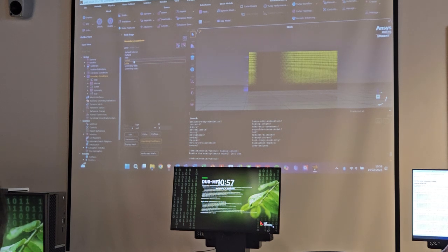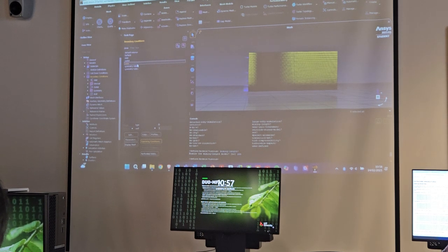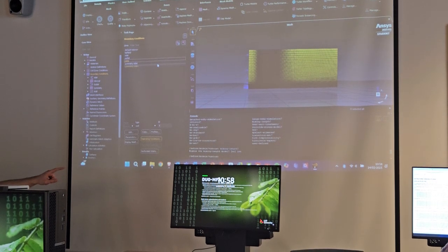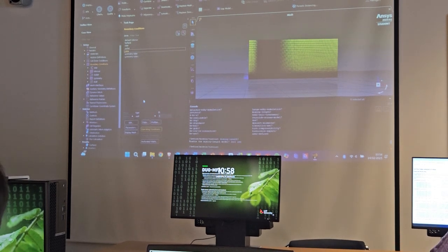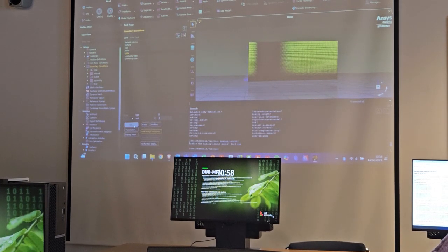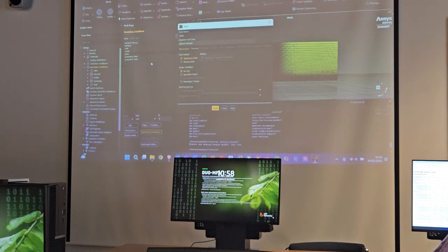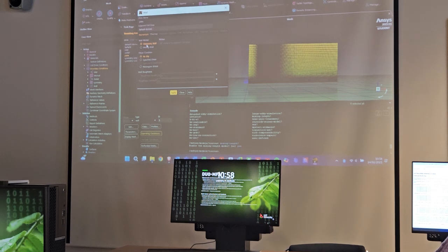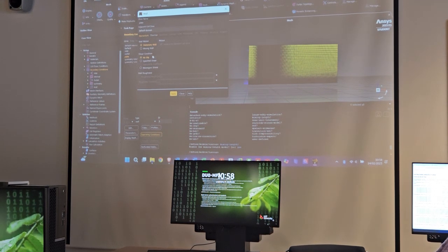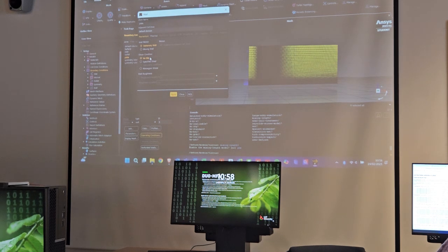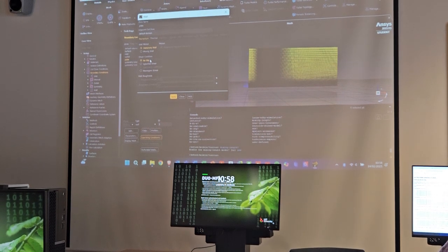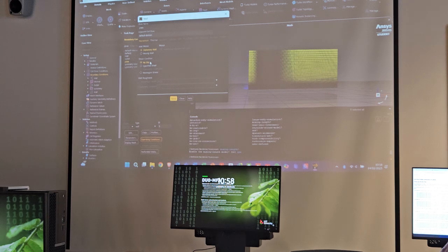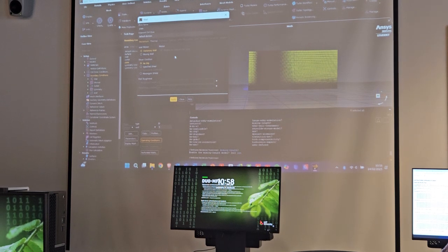Then we move to plate. The plate is the solid adiabatic wall. Edit. Here in the momentum tab we can set that this is a stationary wall, so it's not moving. Then the shear condition. We said this is a no-slip wall, since the relative velocity between the fluid and the wall is 0. So we leave it as it is.